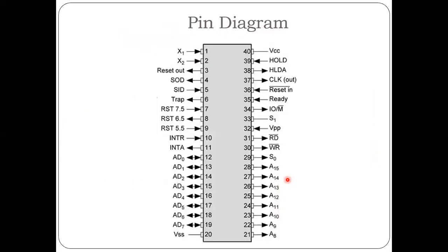So till now we discussed two topics, that is the 8085 architecture. We saw the different kinds of functional blocks and the pin diagram of 8085. Why the pin diagram is most essential: if you are connecting the IC with any devices on a PCB board, we need to know all the pins. If you give a reverse power supply, it will be very dangerous to the 8085. Then we need to know the different operations of the pins.